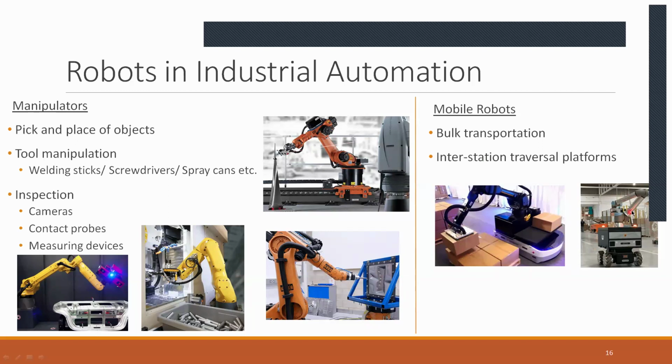If the factory has found it financially unviable to have a robot manipulator at each of these stations, perhaps because these stations might not be working all at once, then it might be financially viable to move a single manipulator towards all of these stations and have it operate whenever it's needed. The human can be moved out of the loop by using a mobile robot, which will carry the manipulator from station to station whenever it's needed.